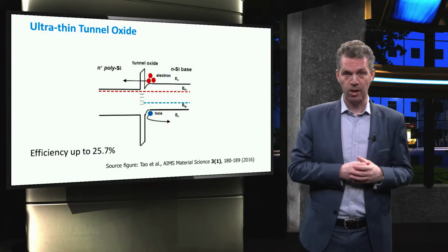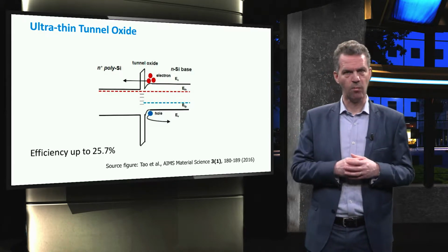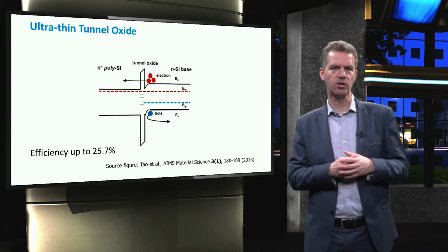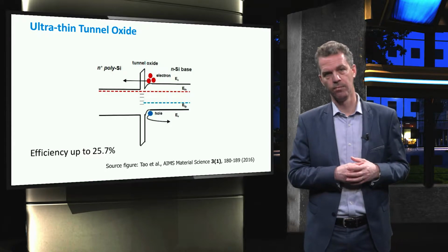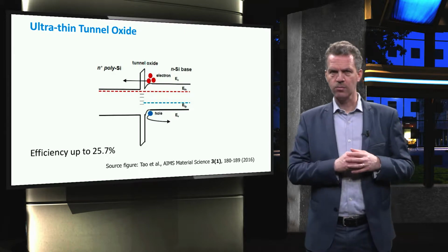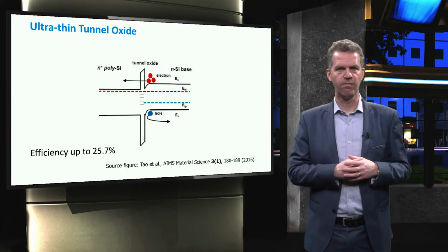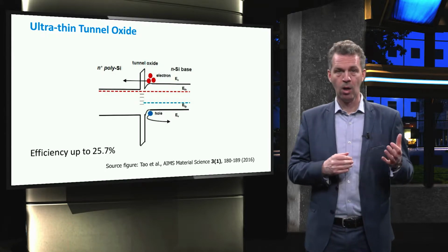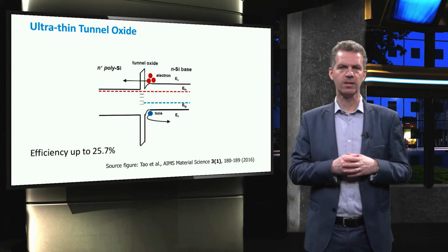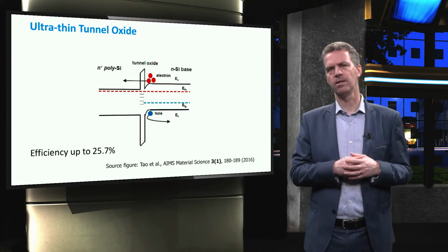Since the oxide layer is present, it is almost impossible for the minority carriers, which are holes in the N-type wafer base, to reach the back contact of the cell, as they cannot pass the potential barrier introduced by the oxide layer. On the other hand, since this layer is kept very thin, electrons are able to tunnel through the barrier and be collected at the back contact with virtually zero loss. Contact patterning, which is a relatively difficult and therefore expensive processing step, is thus not necessary, and the backside of the wafer can be entirely metallized.